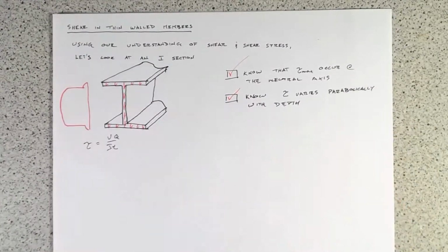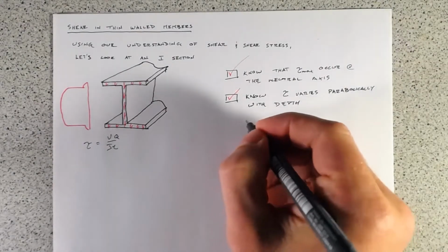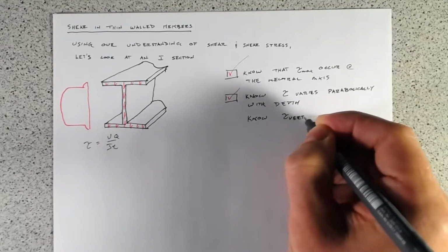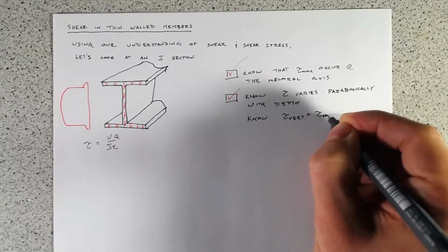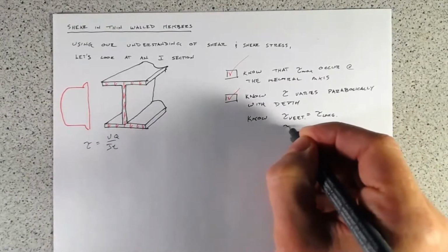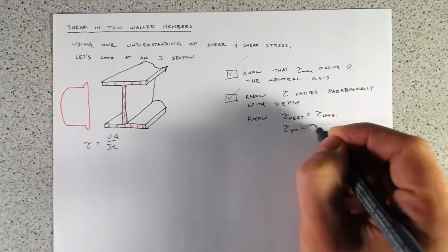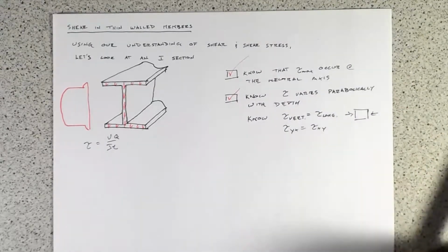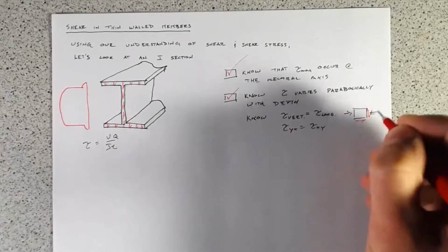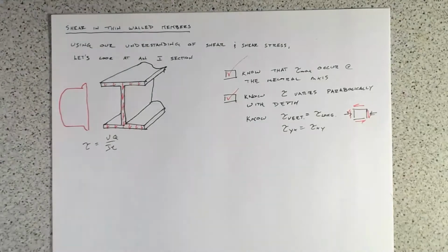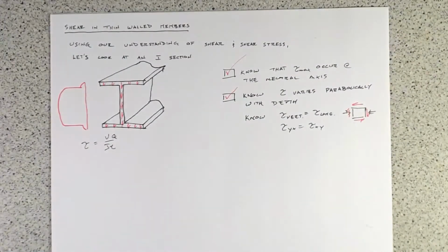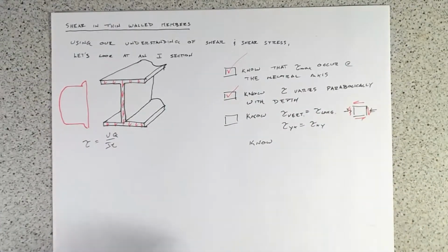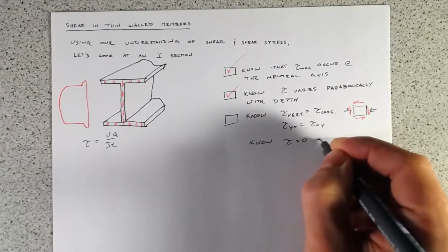Let's have a look at the last two points, and then we'll have a little discussion on whether they make sense or not. We know that our vertical shear stress has to equal our longitudinal shear stress. That goes back to tau yx equals tau xy. You remember our little model here, and I'll draw our shear stresses in red. Remember, that's there for equilibrium. That's this rule right here, so we've proved that it has to be correct. And we also know, using the same model, that tau equals 0 at a free surface.